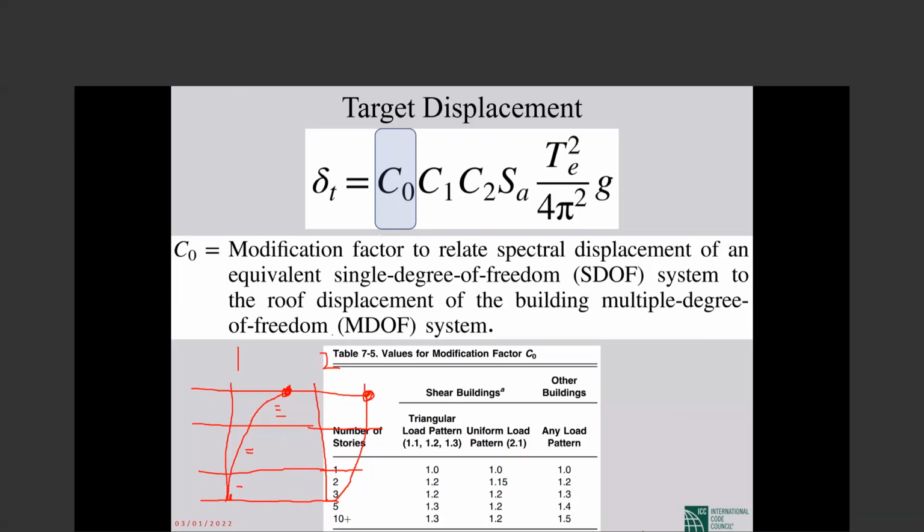But opposite to that, look at type 2. In type 2, you look at the first story, bottom and top of the first story. The difference in deformation is too much. The first story drift is too much. Second story, bottom and top, much less. The third story is almost the same, much less.